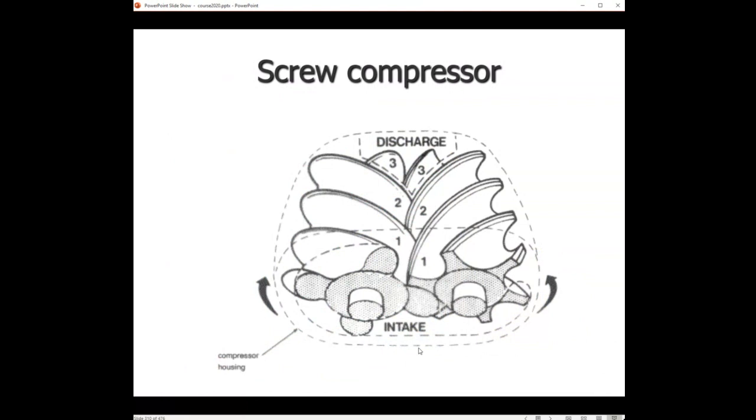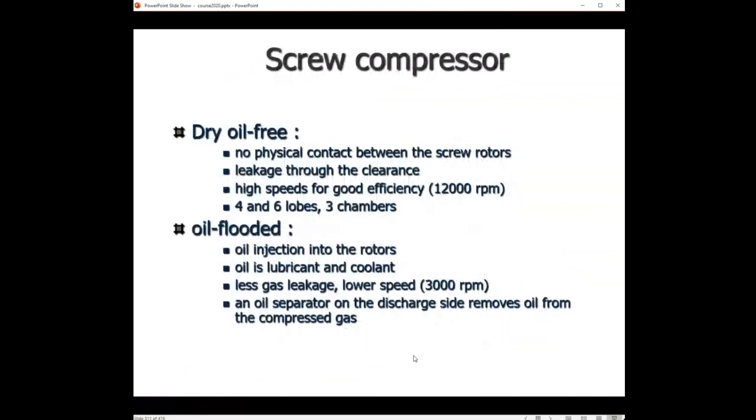Okay, the second type of compressors is mainly used in the cascade system, because in the cascade system you don't need these high pressures because your cooling is better. There we will use the screw compressors. Screw compressors are just screws running at high speed and pushing the gases in one direction.